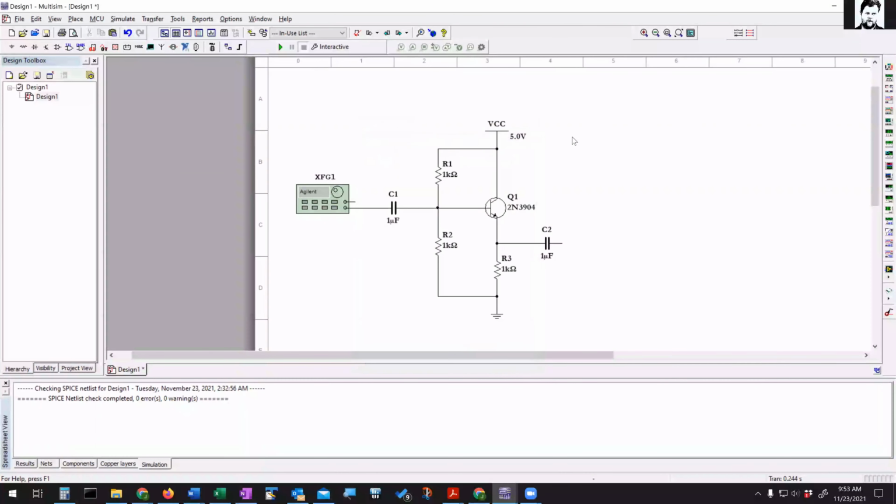And I think it was a 15 volt supply. Setting up the DC biasing point is a little different in this circuit because it's a voltage divider, but there's no collector resistor. There's not going to be any drop over here. So remember how we said that we often want to set up our DC biasing point so that VCE is roughly half of whatever the supply voltage is.